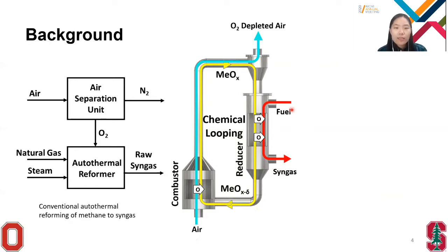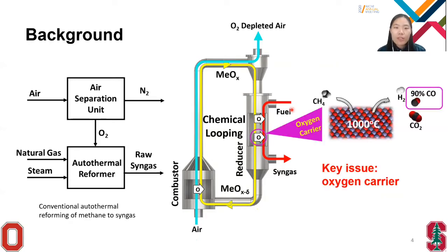However, the success of this process highly depends on the oxygen carrier. Currently, the conventional oxygen carrier requires a temperature as high as 1000 degrees C. This can cause problems including sintering effect, carbon deposition, and morphology evolution-induced mechanical strength deterioration. So it is of great economic interest to decrease the reaction temperature.